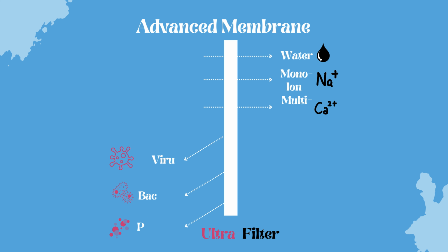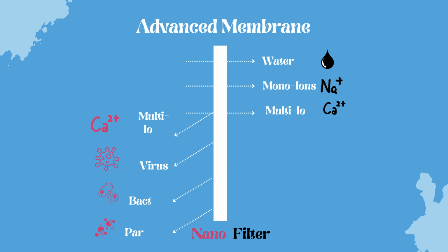Now let's unveil ultrafilters. Ultrafiltration membranes have pore size smaller than microfiltration types. It's better than microfiltration and it can remove even the largest viruses. Now let's shift to introduce nanofiltration, a breakthrough in filtration. Nanofiltration membranes have pores smaller than those used in ultrafiltration, but larger than those in reverse osmosis, so it's effective in taking on viruses with accuracy, though less effective against ions.